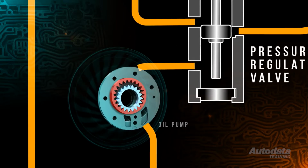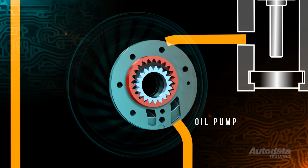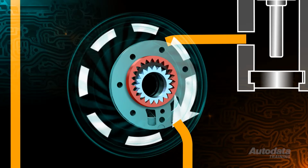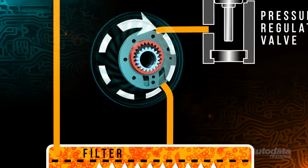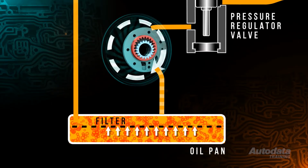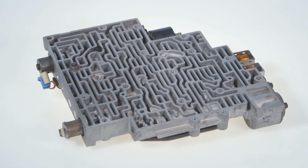A fluid pump is responsible for producing flow within an automatic transmission. It's generally mounted in the front housing and driven by the torque converter when the engine is operating. Fluid is drawn from the pan and through a filter before commencing its journey to the pump. Transmission fluid is pushed from the pump to the valve body for operational control and to rotating components for lubrication.